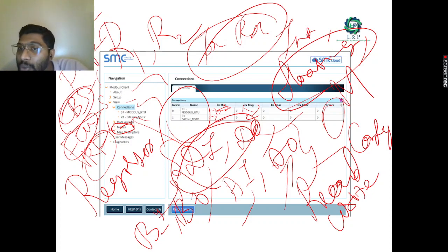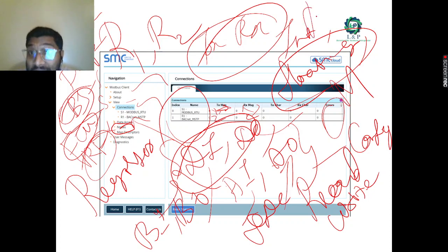Then what you have to do, you need to create the memory arrays. You have to move the information from the slaves to the arrays which are created inside the field server. Then from there you need to move the information to the concerned controllers that you want. It can be a DDC controller that you want to see, or it can be PLCs. Inside the PLCs, inside the data memories, once you have created them, you can move it. So this is how the basic concept is going to happen.